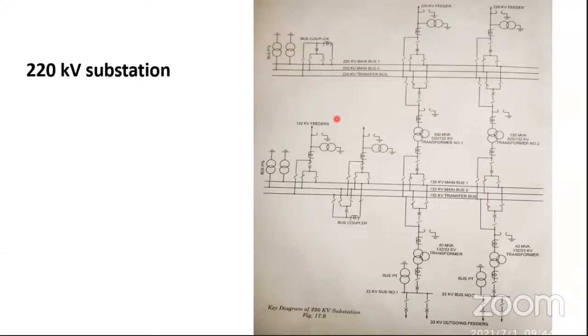Instead of increasing the installed capacity of the transformer, I proposed using two transformers of lower rating instead of going for a single transformer of higher rating, to take the advantage of operating the transformers at higher efficiency and to maintain the power factor reasonable. I proposed that, and our management gave consent, and we could proceed with adequate arrangements required to operate the loads.